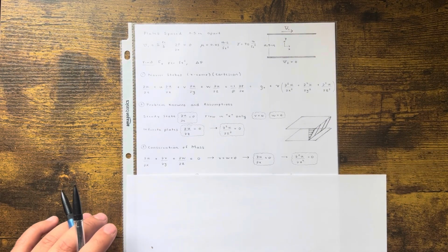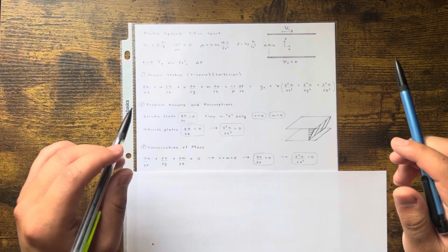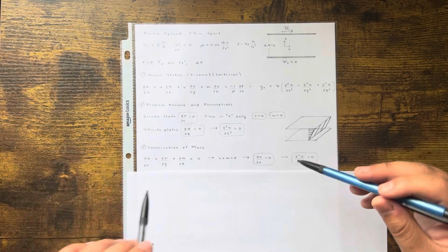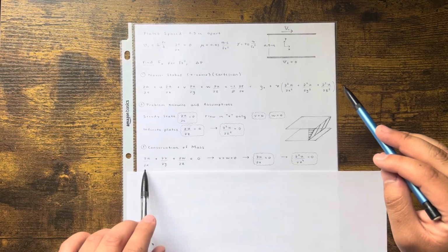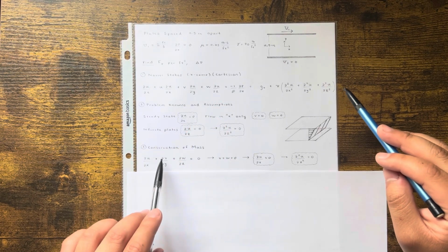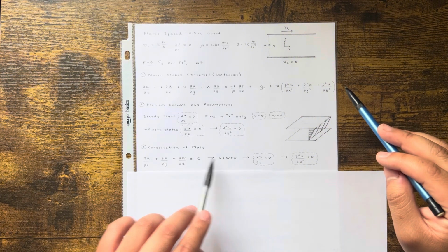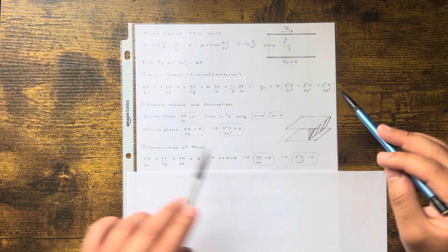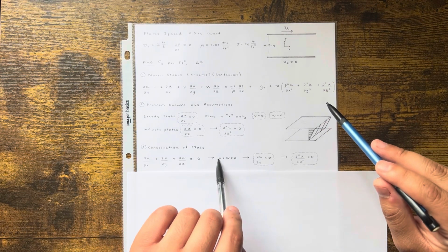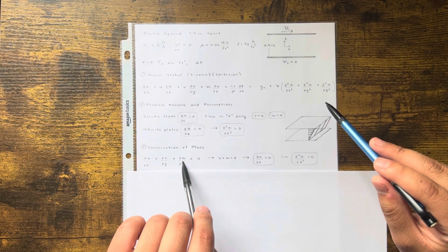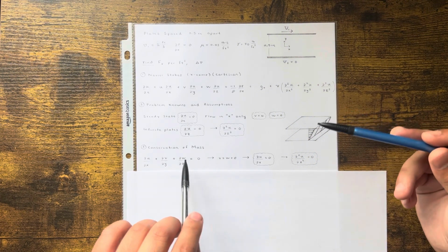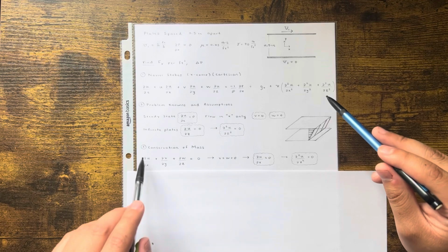Now we're going to go to the conservation of mass. You guys are going to be using this in fluid mechanics for the remainder of the class. I'm sure you've been using it already, but mass is conserved. This is just the conservation of mass in x, y, z Cartesian coordinates. We know v is 0 and w is 0. So take the partial with respect to y of 0. Take the derivative with respect to anything, it's still 0. So delta v over delta y is 0, and delta w with respect to z is 0, because this is 0 already. So that means this is 0.